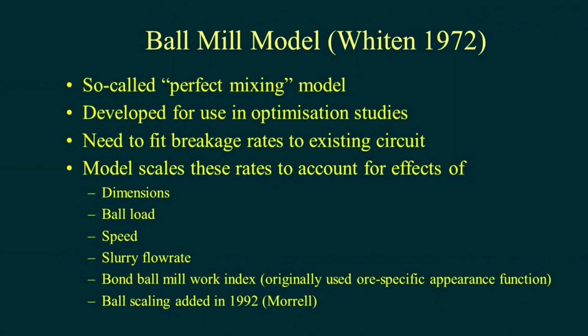because it was not meant to be used for that. One of its problems is that the breakage rate, remember that distribution I showed you earlier, the model doesn't give you that. You as the engineer have to provide that breakage rate distribution. So you're faced with that dilemma. Well, where do I get it from? And the advice is, well, you need to get it from a similar circuit or from a pilot mill test